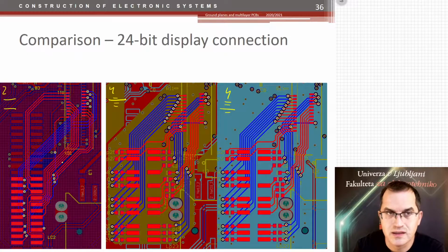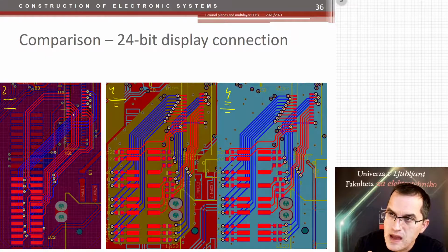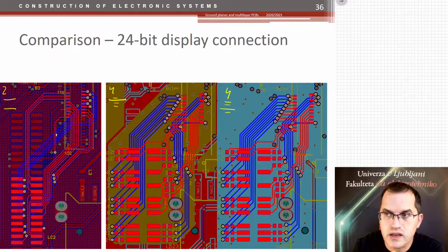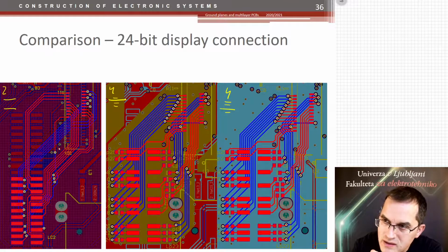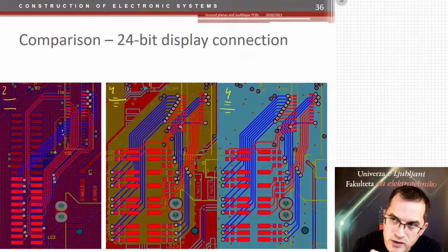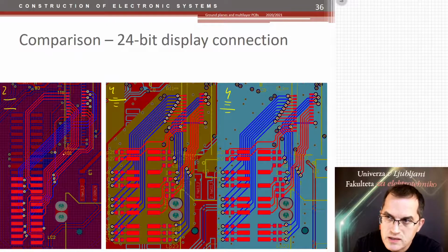The problem was that it had too much electromagnetic noise. So these are these connections. As you see, because these connections have to be at least double-sided on 2 layers, you just don't have a well-defined return path. If this current flows here, then it returns back on the bottom, but here the bottom layer is interrupted, it's broken. And these are tracks on the bottom, and here the top layer of these tracks is interrupted as well. So there is no continuous ground plane anywhere possible here.